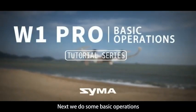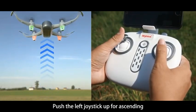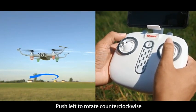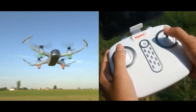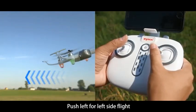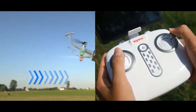Next, we do some basic operations. Push the left joystick up for ascending and pull down for descending. Push left to rotate counterclockwise and push right to rotate clockwise. Push the right joystick up for forward and down for backward. Push left for left side flight and right for right side flight.